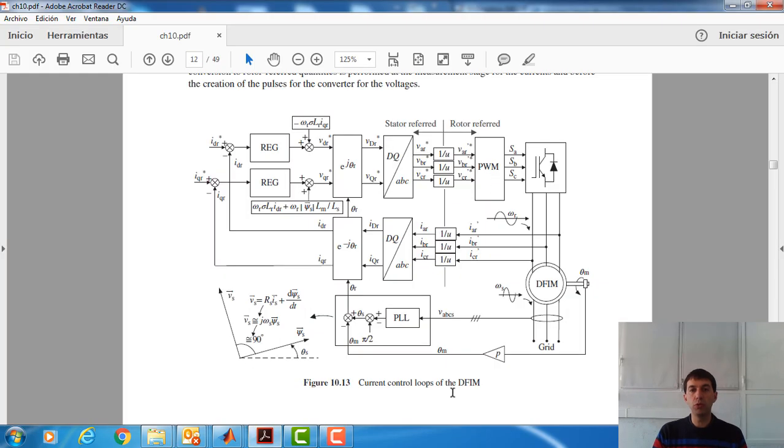But before we do that, let's have a look again at the block diagram that we need to implement. We will start from this side, implementing these blocks. But first, please take into consideration that this normalization is not necessary, because the WR induction machine model of the SimPower library presents the rotor referred to the stator.